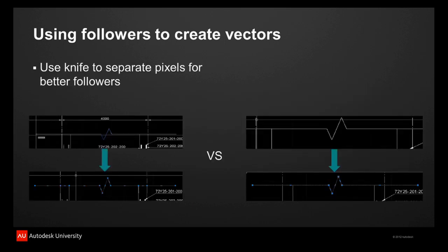That's exactly what I've done here, and I've used this break line that I've got in my existing image as a sample. Just a tip, if you want to write this down, using the raster snaps to snap to an endpoint of a raster is a good idea when doing this, because you want to start from one point and run through in a certain direction all the way to the end. All right, so that's basically what I've done here, and you'll see once I do that, it traces the original line with a blue line indicating this is the line that is picked up, and I can then accept this or reject that.